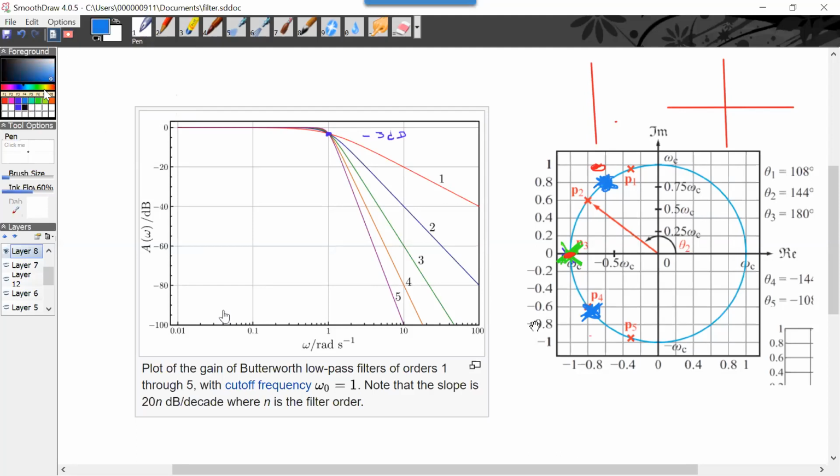So what I did is I have kind of a unit triangle where I'm splitting the poles along the x-axis here. So a first order would be 1 here, a second would split it in half, a third would put this into thirds. But the complex, so I'd have one real pole and then a pair of complex poles, right?